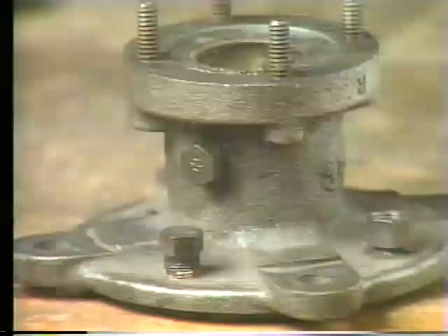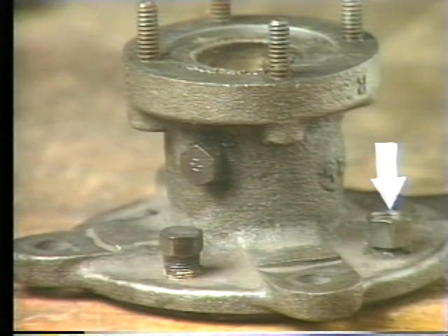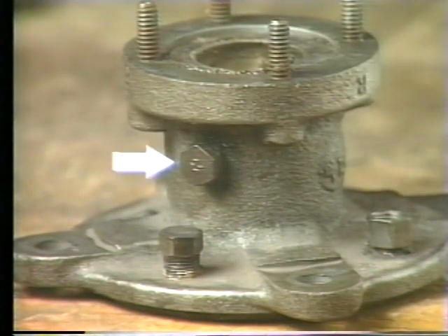Like the other end cap, this one has an air port that allows air to enter and exit the cylinder from this end. This end cap has a plug which can be replaced with a grease fitting so that the piston rod can be lubricated to prevent it from binding as it moves in and out. The piston rod is generally lubricated on a periodic basis.